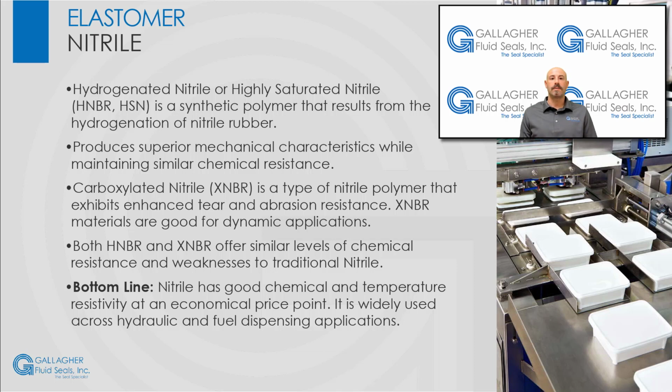Key takeaways are the following. Nitrile is the most used O-ring material. It has good chemical and temperature resistivity at an economical price point. Nitrile is widely used across hydraulic and fuel dispensing applications.